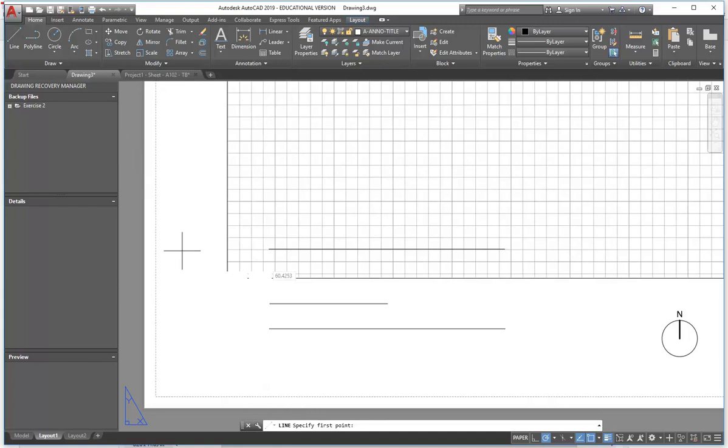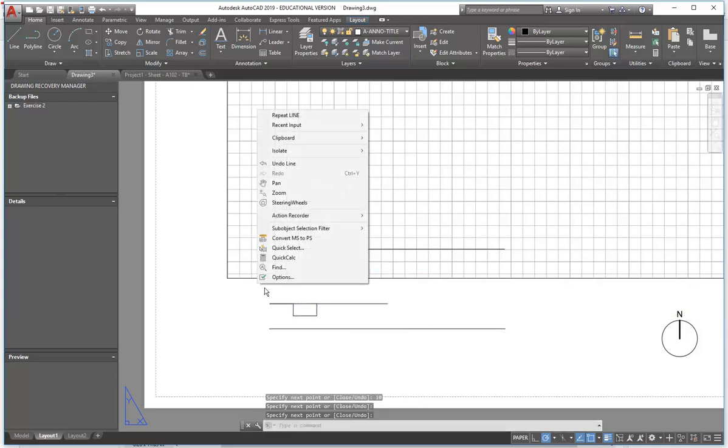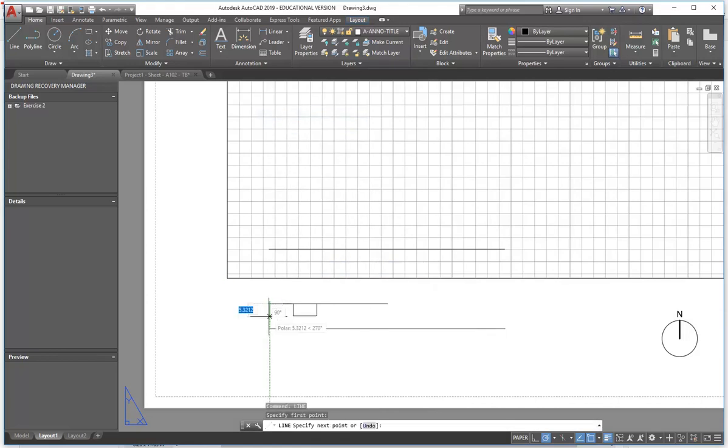Half a metre at 1 to 50. So half a metre is 500 mil. At 1 to 50, it's 10. And then to make it nice graphically, I might make it half of that down, so I'll come down 5, and then come across again, 10, and then back up again. Then I can draw maybe another line starting at the beginning and come down 5.